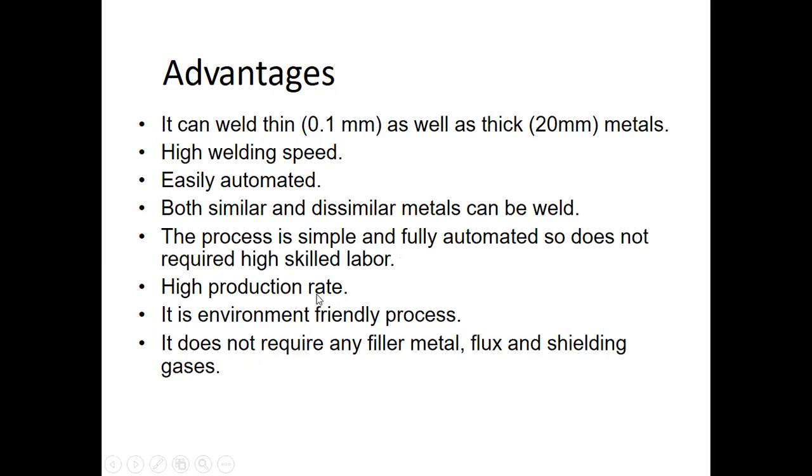It has a high production rate, and it is an environment friendly process. Not many arcs are generated. It does not require any filler metal, flux or shielding gases. Only the resistance between the two weld metals is responsible for creation of that weld nugget.